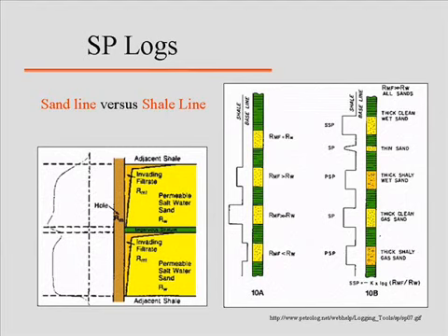One thing to note is that if you have a very thin sand bed, you're not going to see as good a response because the device has its measurements spaced from one another. So a thin sand bed is not going to be portrayed as clearly as a thick sand bed. That, incidentally, is one of the perils of many of the probing devices we have. So a small little kick like this may be all you're going to get.